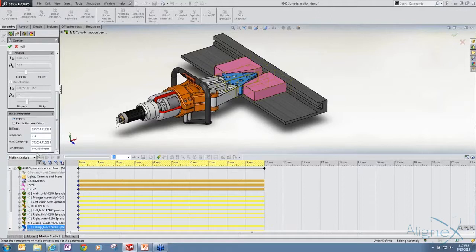And when we have rigid bodies, to allow the solver to ease into the calculation, we can allow a tiny bit of penetration, so those bodies can actually pass through each other by a very tiny amount, 0.0039 inches.